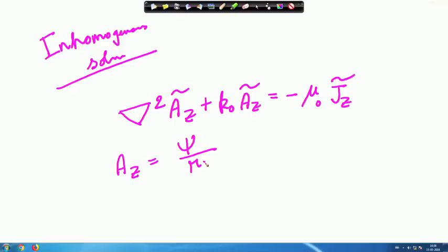If we can enclose the source very near to r, we will get its radiation effects, that means the effect of the source. So, to find the source strength, we integrate both sides of the scalar Helmholtz equation over a small spherical volume of radius r.